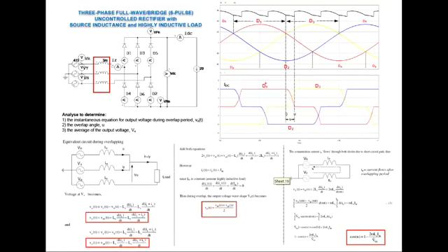The current through D1 will reduce at a certain rate from IDC to 0, and the current through the yellow phase will rise from 0 to IDC at a certain rate. There is an overlap of current during this transition, known as the overlapping period, from 0 to u. Sometimes it is known as the overlap angle u.